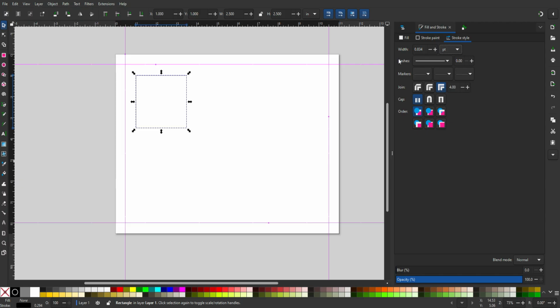And that, for our line weights, is what we want to be using. Now, this is for laser cutting specifically, but if you were doing a different kind of project and you wanted your stroke to be in inches so that you could see, like, I can change it to a 1/4 inch stroke, and now the line has gotten much thicker. And here you can see the corners. You can round your joints.